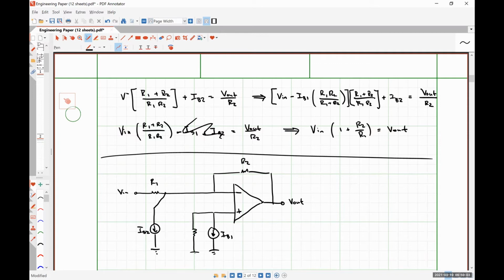a resistance R1 in parallel with R2, and we connect that in series with our non-inverting input. So we're always adding the correction to our non-inverting input. And if you go through the math, which I did, but I'm not going to force you guys through, we get a transfer function of V out is negative R2 over R1 times Vn, which means we're completely nullifying the effect of the bias current by doing the exact same correction.